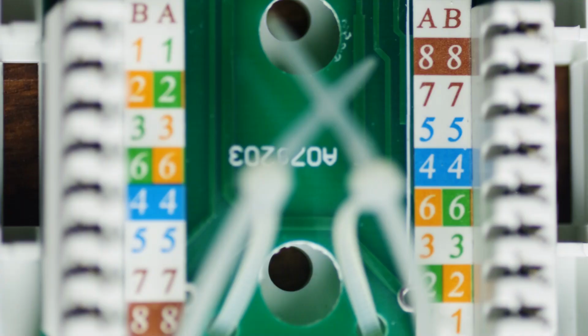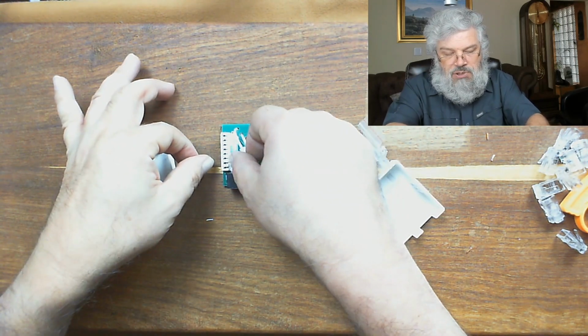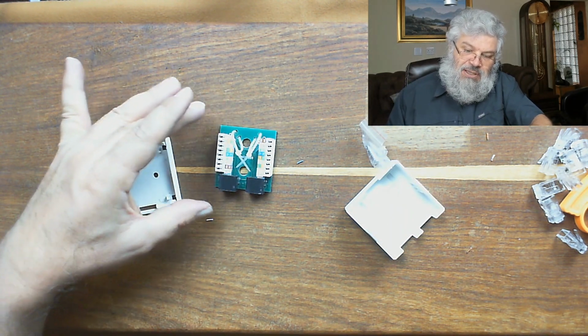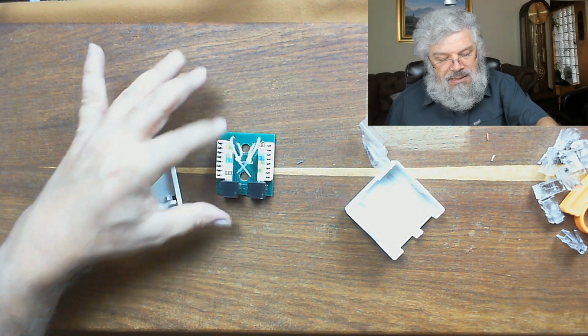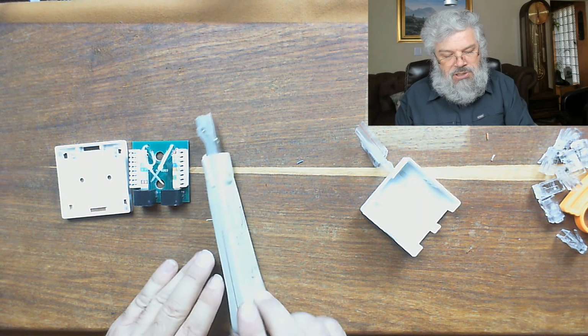What you will see here is that this has two sockets, and on both ends you've got both of the wiring schemes and the color of the wire that needs to go into that little slot. So it's basically a matter of pushing the wire into every slot and then using a punch down tool to get it into position. Now, there are at least 3 different variants of these sockets, so for that reason you have to pick the appropriate punch down tool.